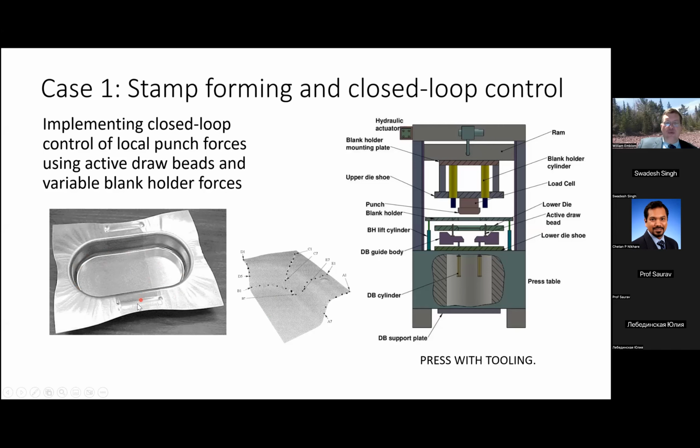And this is like one step more complicated than standard cup forming. And you can see over here that shaded area all along here. Those are actually grids that were used for measuring strain. And then you can see a quarter FEA model over here, and you can see different paths from A to D. We use those to study the strain effects in various locations.